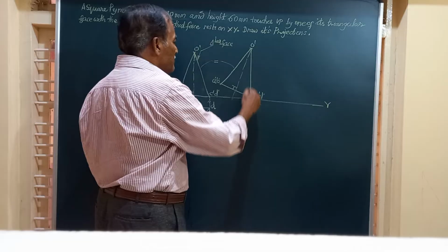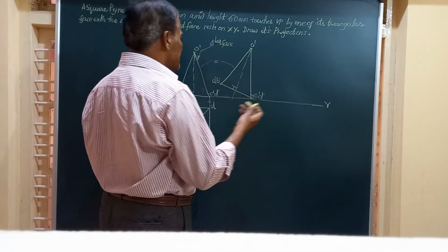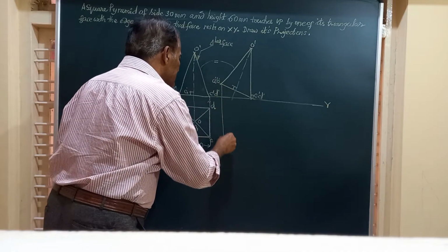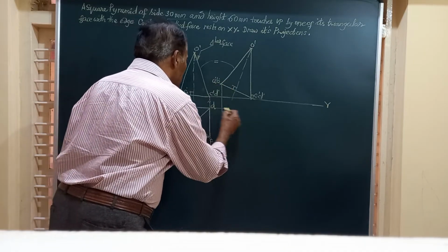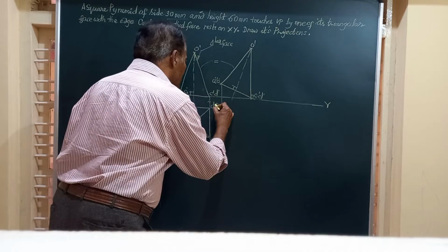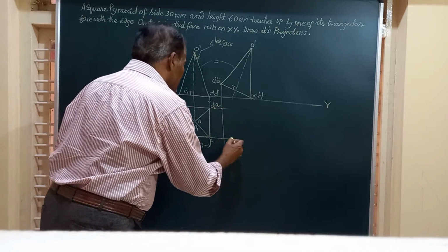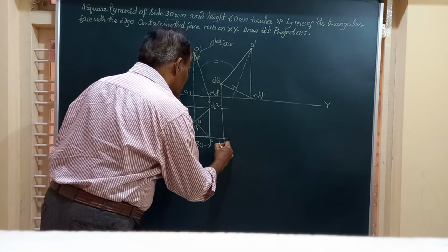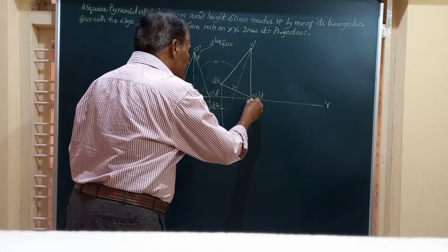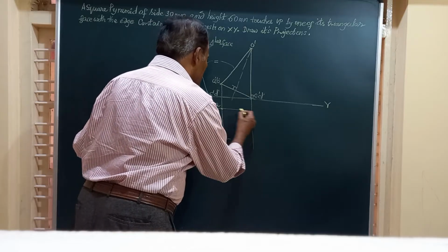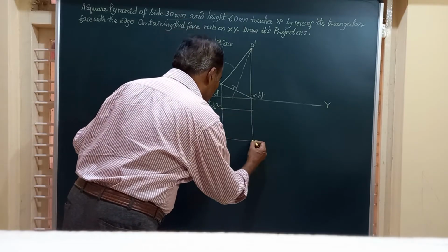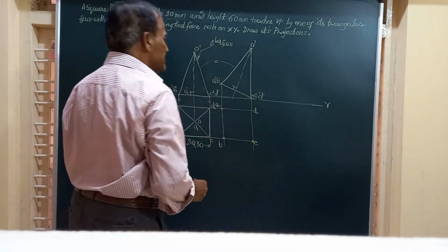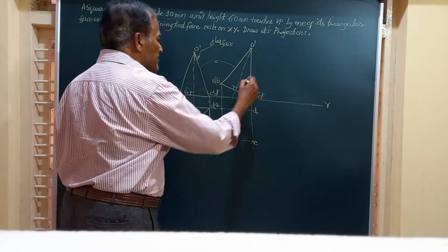Now friend, this has become perpendicular now, and let's see how the top view appears. So we'll just draw the lines from there. Vertical from A, horizontal from A, the point of intersection is A. Likewise, vertical from B dash, horizontal from here, this gives you the point B. Similarly, you get for C and D. So you go in order. A, B, this point is going to be C, and this is point D. So A dash, A, B, C, D you have got.